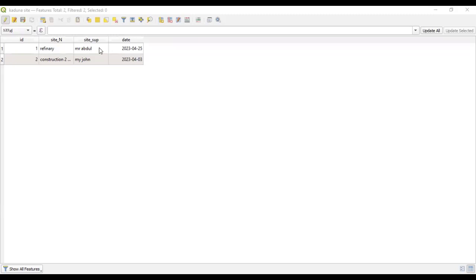Then what about precision? I saw you put 1.2. No, I did not put 1.2. Precision is, for example, like your decimal place. If you are calculating length now, maybe it is 2 meters, and you discover that possibly there's a small extension from 2 meters, which is maybe 2.5. You discover that if you put 0 precision, it will just write 2. It will automatically approximate it. Well, when you put 2 precision, it will write 2.50.